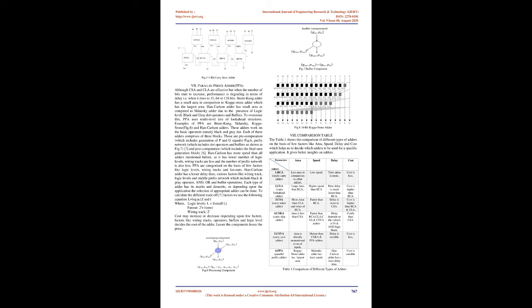Here the adder uses the carry of one FA block with the sum of the second FA block to get the sum. As shown in the upper part of the diagram, the important point is that the sum and carry are calculated individually and not simultaneously. Firstly, the sum is calculated without taking carry into consideration. Then the adder calculates carry by leaving one space from the LSB side, as there is no carry at the start. After the sum and carry values are calculated, the adder adds both of them together to get the final number, as shown in the lower part of diagram 5.